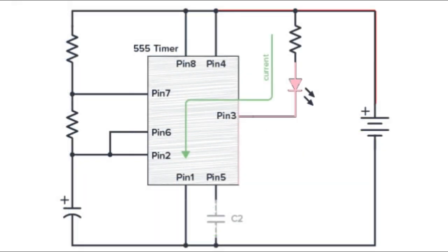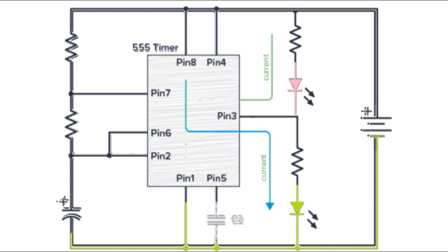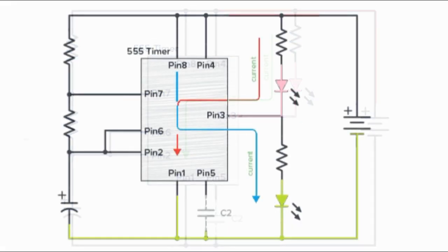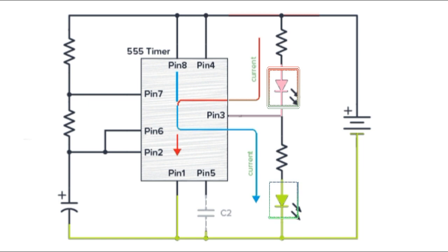The ability of the 555 timer to both sink and source its output load current means that both LEDs can be connected to the output terminal at the same time, but only one will be switched ON depending on whether the output state is high or low. The two LEDs will be alternately switched ON and OFF depending upon the output. Resistor R is used to limit the LED current to below 20 mA.